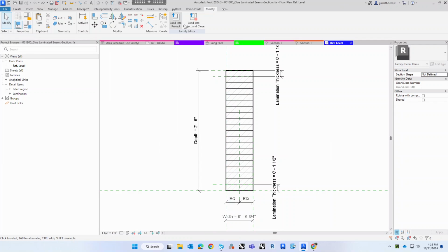You can create new ones. You can put different line patterns on, colors, line weights. But within families, they were like, we shouldn't put it, even though it still has additional settings. When you try and click on it, it doesn't work. So they literally try and fake you out. However, you can still add line types to your project. It is under object styles. So if you want to create a new line type, you can just create a line and then put whatever line type, whatever color, whatever line pattern on there, and then associate that to whatever element you're putting on there.